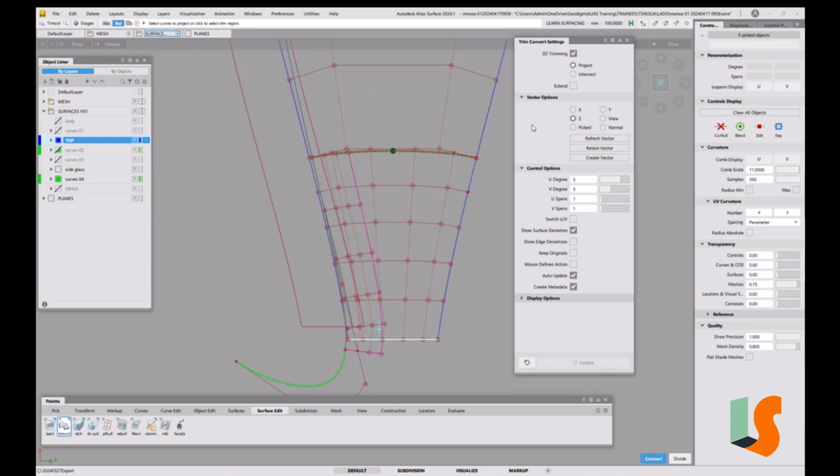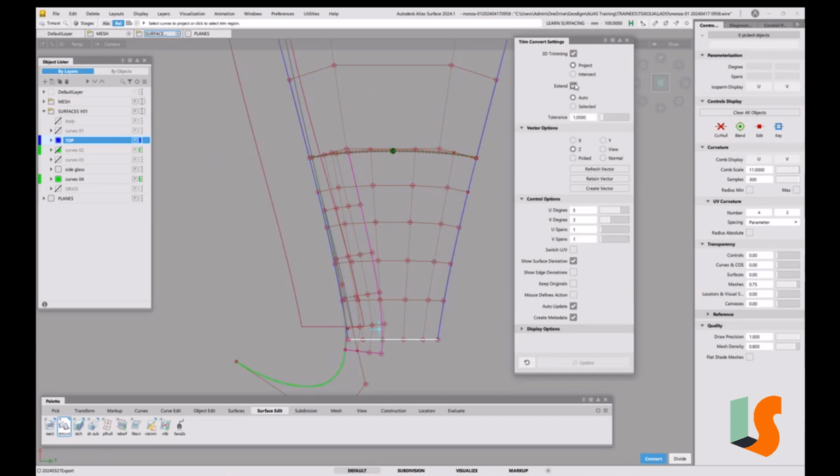We can extend that in the function if you go into extend. I've never had any luck with auto. The idea of auto is it should allow you to do auto and then a tolerance. So if I said 10 mil, extend this 10 mil, that's what I'm saying, and then say convert. It works now. Finally, they fixed it because in all previous versions that never worked.